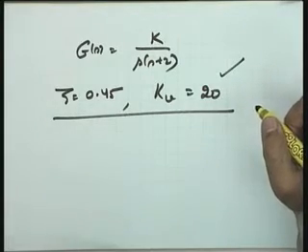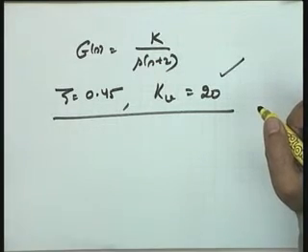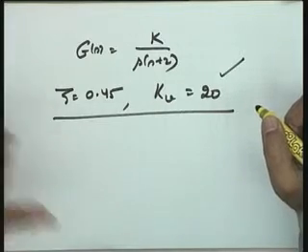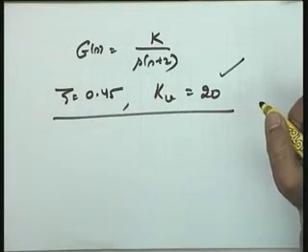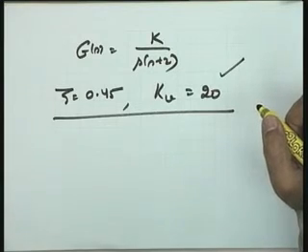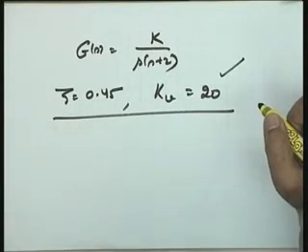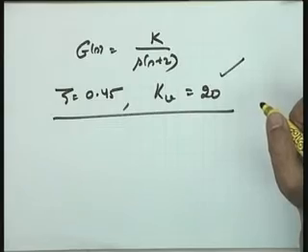I will put this question to you: if the steady state requirement using a phase lead compensator is not satisfied, what do you propose? This is my question to you, and I will end my discussion with that question only. Please keep that question in mind. You recall that in phase lead compensation, the steady state error requirements were not specified because it was type 2. But suppose it is type 1 and steady state requirement is specified and it does not meet that requirement. Then what do you do? Because any adjustment of pole and zero will only marginally change that requirement, will not satisfy that requirement. So this is my question to you, please. You have to answer it.